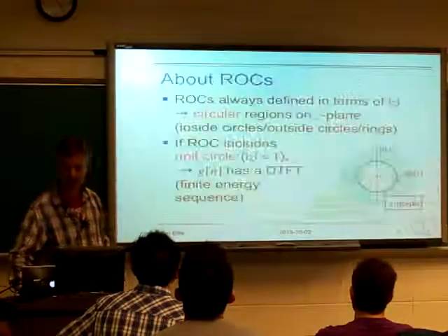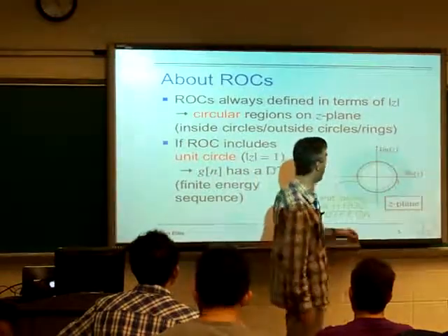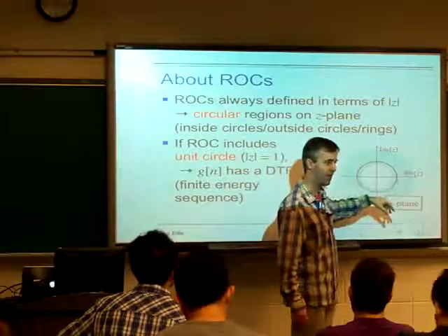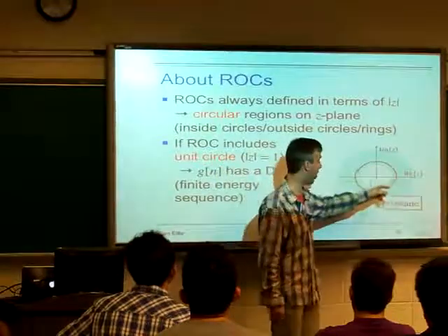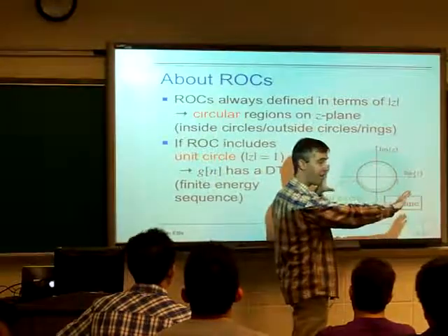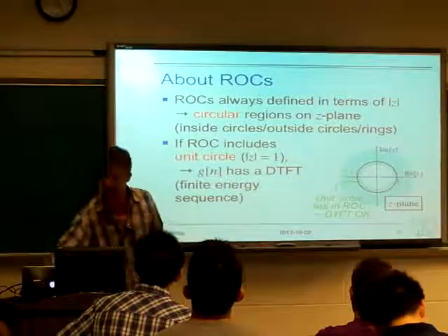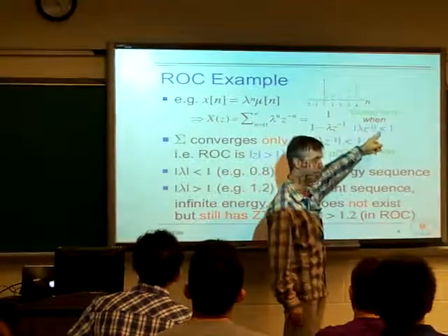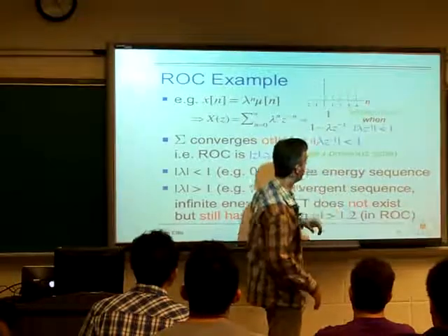And so that gives us this concept of a region of convergence. And so we can typically draw it like this, that here's the whole z-plane. Now we're looking at that plot from above, and the shaded region is the values of z for which the sum converged, and then the blank values are the values of z where it didn't converge, and so they're the part that are not in the region of convergence. And this is the picture that we saw, right, that there was some circular region: for values of z outside, larger than that circle, we were okay, and then for the values of z inside, we were not. And that's exactly this case, right? So the constraint is that lambda divided by z needs to be smaller than 1. So as long as z is large enough, then that ratio will be small enough and we'll be okay.